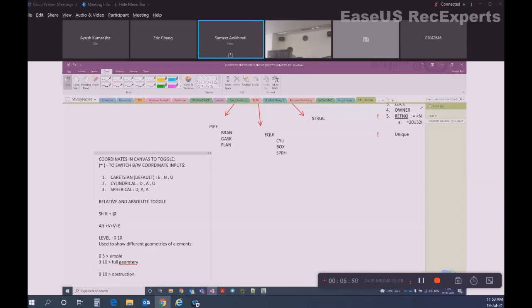9 to 10, any primitive. For example, you want to make a tube bundle removal space for a heat exchanger. You make an obstruction volume for that, and you assign the level 9 to 10. How that is assigned, we'll see in individual training.